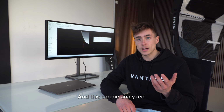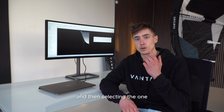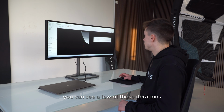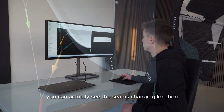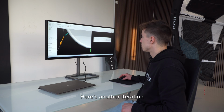And this can be analyzed by simulating many different configurations and then taking out the configuration that is the most resistant against buckling. So here, for example, you can see a few of those iterations. If we zoom in on the wingtip, now you can see the seams changing location actually. Like this. There's another iteration.